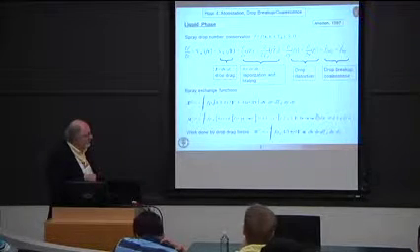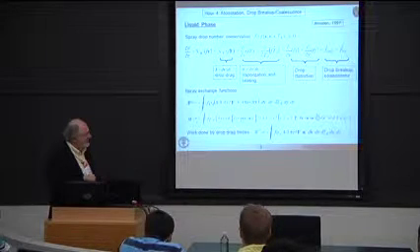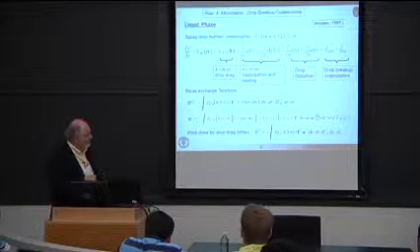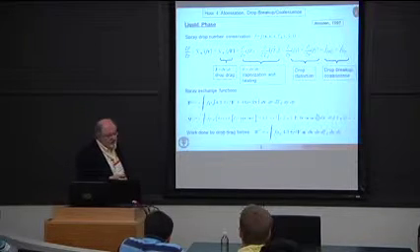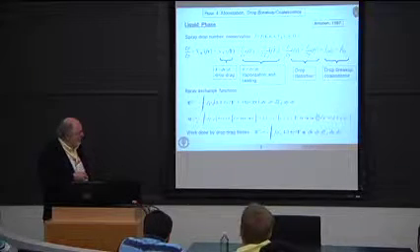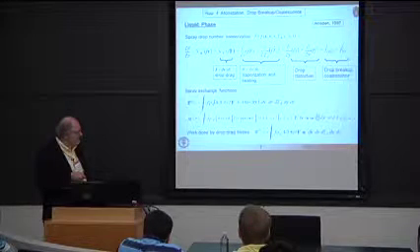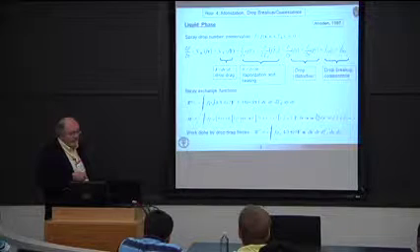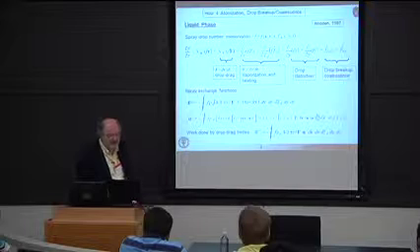And then finally, we have a work term here, which is basically the drag forces times the difference in velocity between the droplets and the gas. I'm going to talk more about turbulence modeling a little bit later, but this U prime that you see here is an attempt to try to include the effect of turbulence in this work term. So when you look at the turbulence equations, you'll see there's also a source term associated with the work done by the drag forces. And that's this F dot U prime term here, the drag forces times the fluctuating velocities of turbulence.